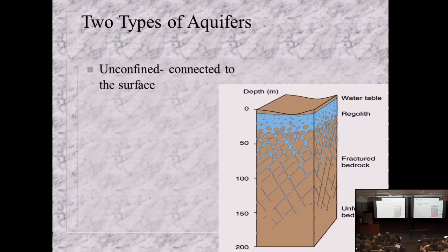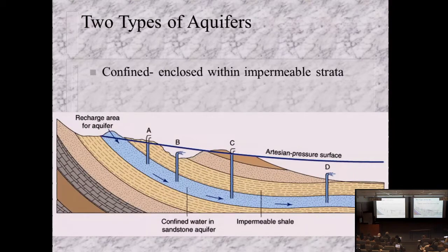They're all open to the surface. They're actually quite difficult to mathematically model because one of the first things you need to know in an aquifer to do modeling is the thickness of the aquifer. And as soon as you start pumping it, you change the thickness, the saturated thickness. So it becomes this iterative, pretty high level calculus stuff. So really easy for us to work with, but difficult for us to mathematically model relative to these.